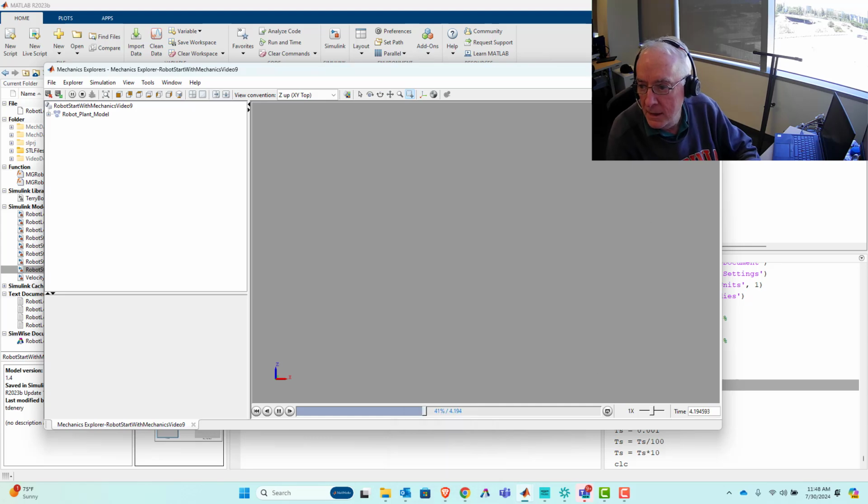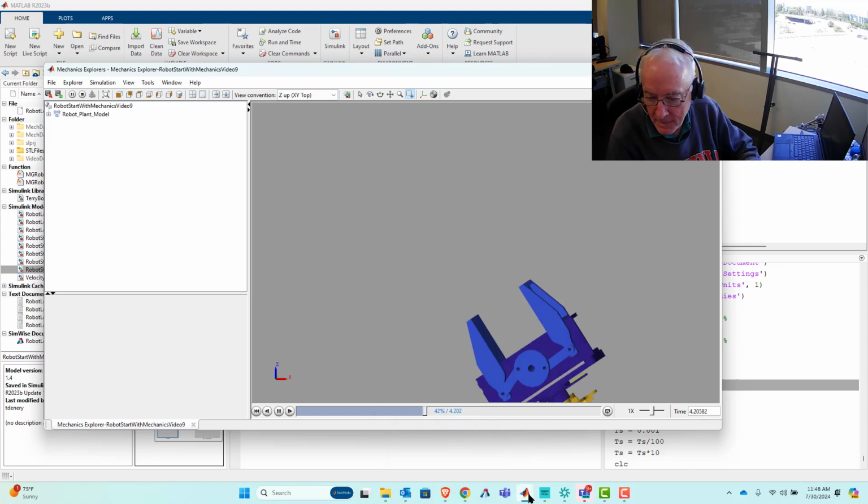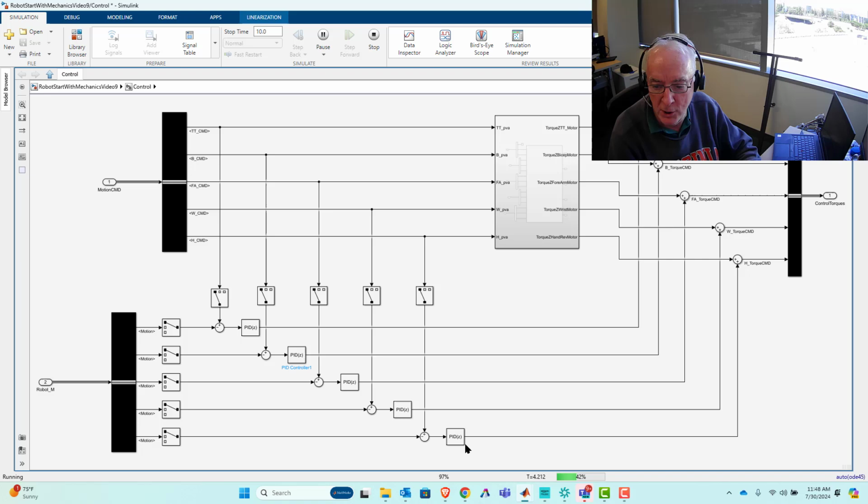All right. And I could scope all these things and I could show that, perhaps on error, this is the first one that gets big, but I'm not going to worry so much about it. And so hopefully you're with me and just saying, yeah, the problem is that hand controller. You see it right there. It's this PID that's going to contribute the feedback adjustment on the torque that will be delivered through that hand motor, right?